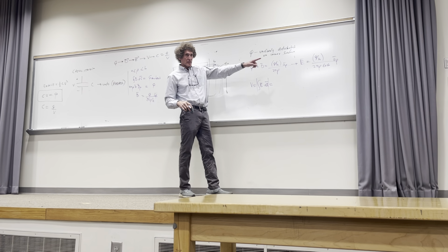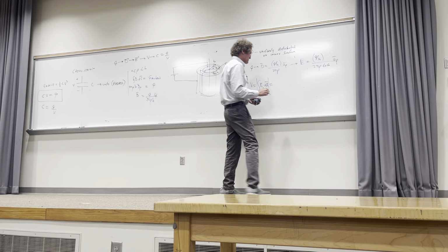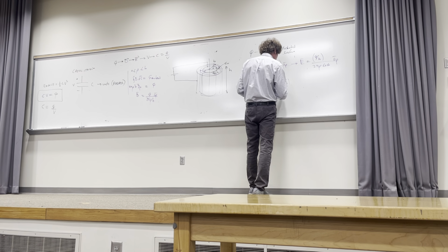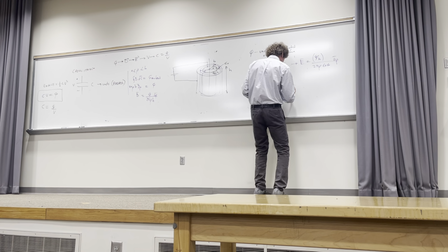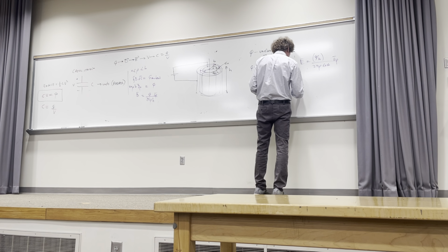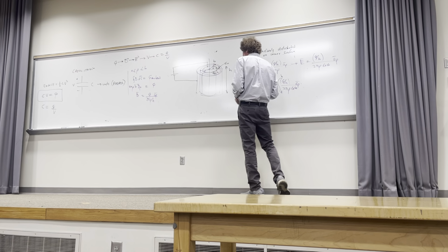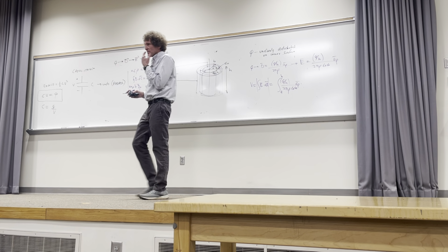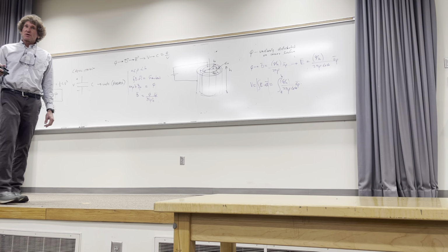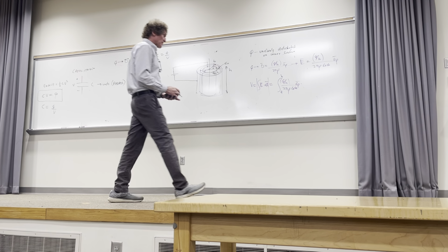Well, I've got to integrate that from A to B of Q over H, and then you have 2 pi rho epsilon relative epsilon naught a rho. And what's dl in cylindrical coordinates? Do you remember the differential length? There's only one portion I care about. It's going to be d rho a rho, right? That's the first part.